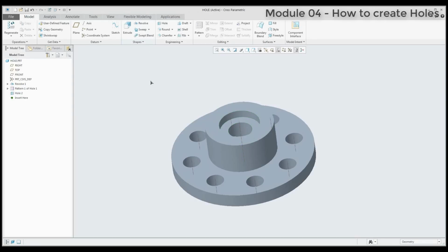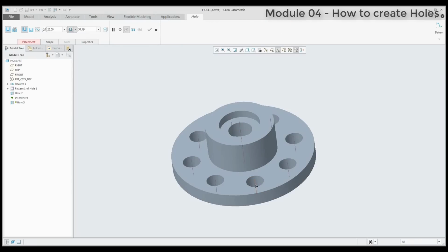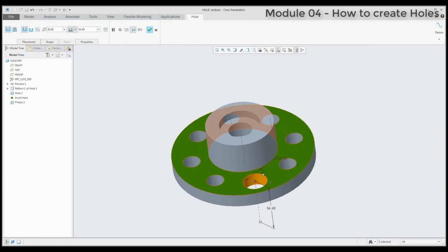Same logic we can use on existing one. Yeah, so create a hole, and with control button I will select axis and start surface. We can change the shape and depth. Yeah. So I will create something like contour board, but it will be more than one feature in the model tree. It doesn't matter. The Creo is feature based, so it's much better if you create more than one feature. You can really easy modify this feature directly and found it.